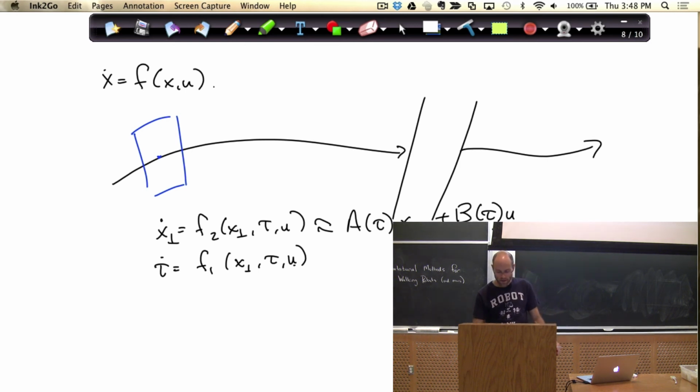Okay. If I line up my switching surfaces with my transverse coordinates, then I can solve through impacts and the like, and I can do LQR along a trajectory. And the result of doing it in these reduced coordinates is to get orbital stability of the closed loop system.